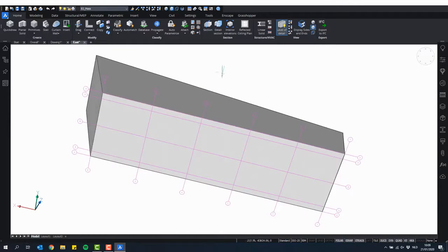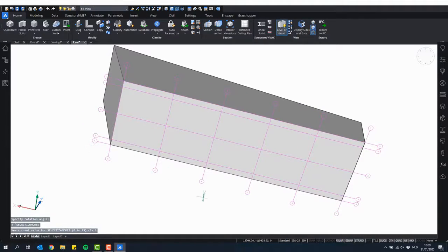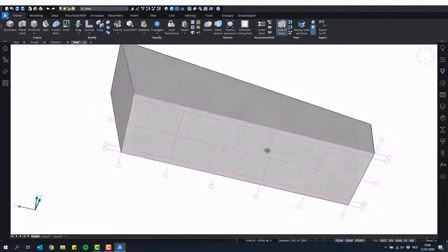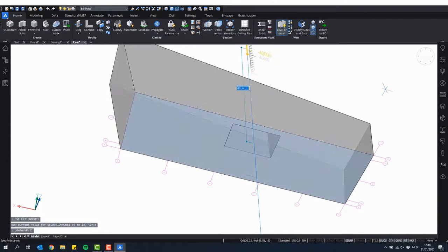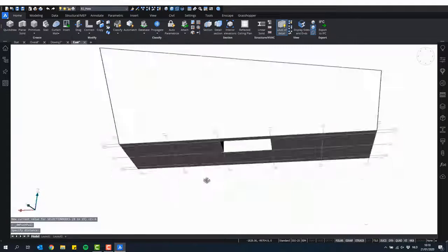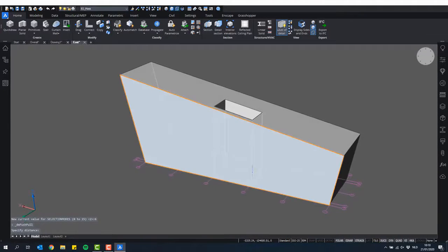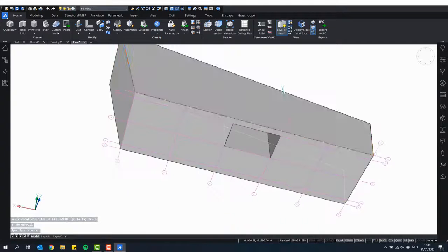What I'm going to do is enable my face detection. Oh, sorry, my boundary detection. And you see now, because there is a grid on top of this bottom face of this building, when I move my cursor inside one of those grid cells, the boundary is detected within this grid cell, the boundary on top of this solid face. So if I hover over this boundary and in the quad click, for instance, Push Pull, you see I can push pull a hole in this solid with this shape. Actually, this is not what I want, so I will undo. I will Control Z.